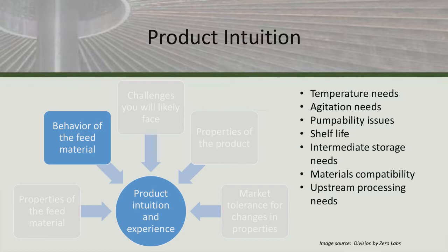And also, what upstream processing needs do you have? Does it need to be homogenized? Is there blending? Is there a brewing step or an extraction? Anything that requires equipment beyond a basic mixing tank, that's something important to think about and identify as early as possible. There's a good chance you may have to provide that equipment.